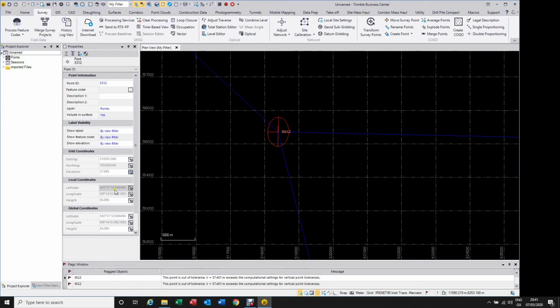You see these coordinates are WGS84 and these are the GRS80 local ellipsoid, and that's the cylinder, the Israeli Transverse Mercator projection, the grid coordinates. Just compare the two ellipsoid coordinates, they're pretty much the same. If you see, north changed very little, maybe even less than a millimeter.